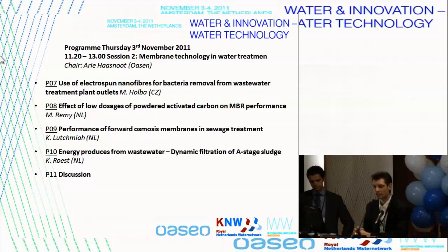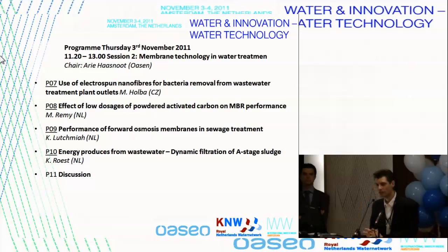And then about the energy, you're right. If you use, for example, a salt for forward osmosis, then the forward osmosis module will be energy friendly because it's a natural process. But after that, you still have to reconcentrate your salt and produce your clean water, and that's usually an energy intensive process. You could apply, for example, reverse osmosis or other desalination processes if you use salts in your draw solution. And in our project, sewer mining, we could gain some or maybe even all of the energy from the organics from the sewage. So that's why it's an interesting whole concept.